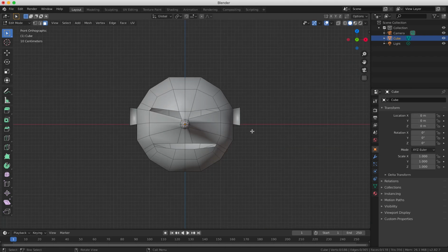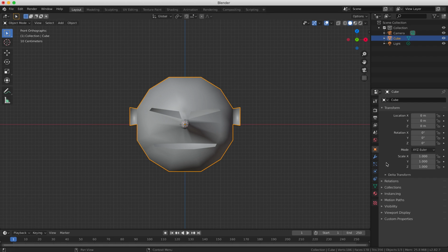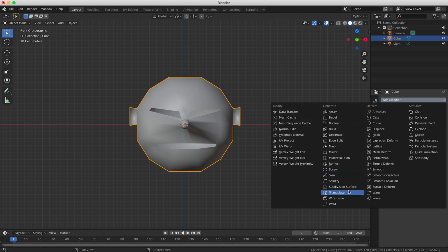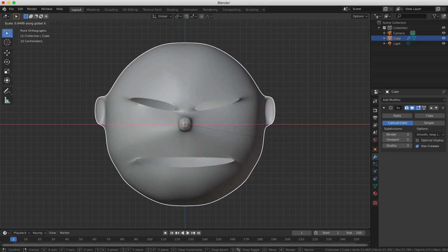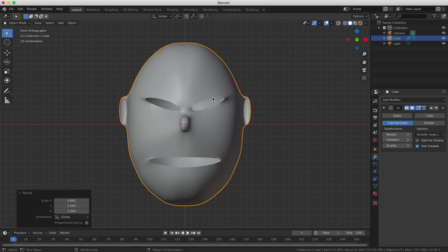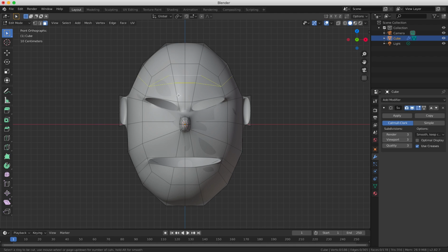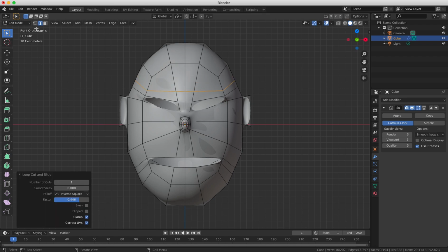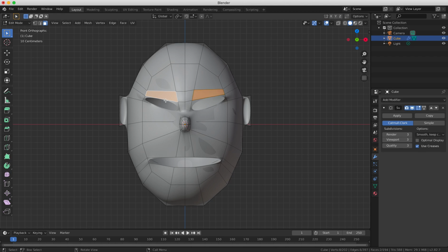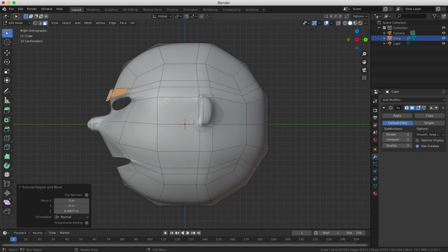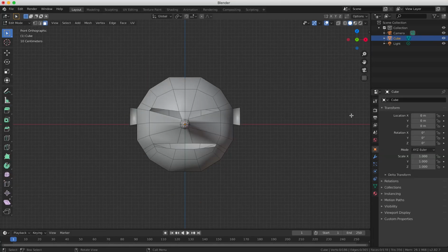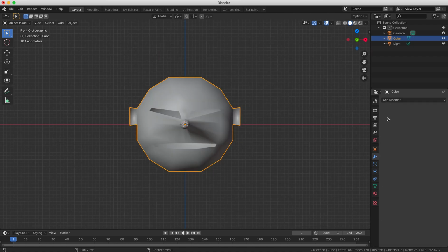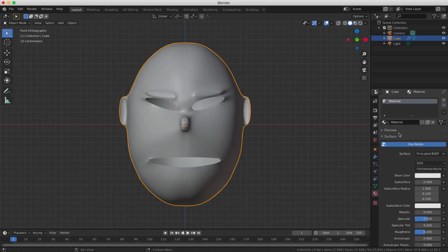Next, we're going to open the Object Modifiers tab in the Properties window. And next, select Subdivision Surface from the Object Modifier options to smooth out the cartoon face. This is known as a Subsurface Modifier, and Blender works out the mathematical equations to make the object appear smoother. You can increase the number of subdivisions, but generally it's not advisable to go above 2. Compare the old head with the new one by switching on and off the modifier. As we can see, the new one is much smoother and more detailed.